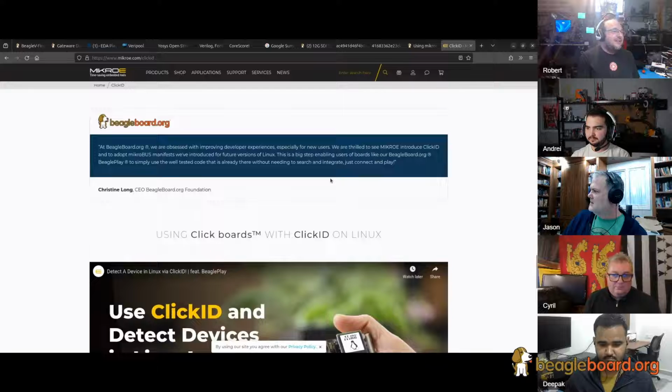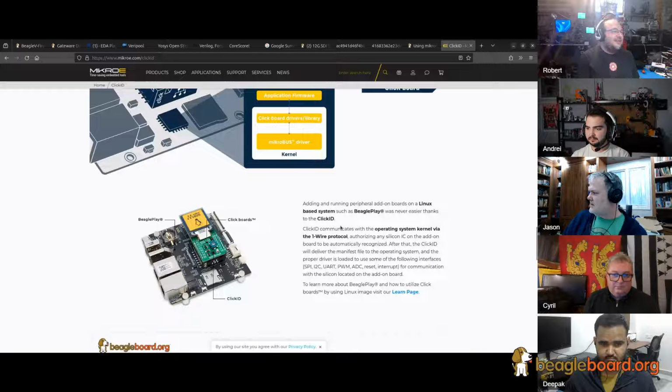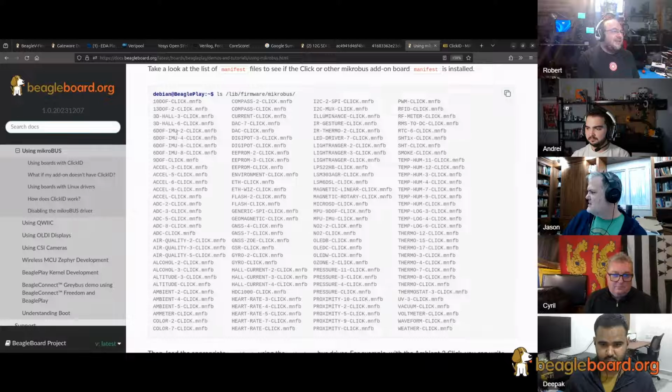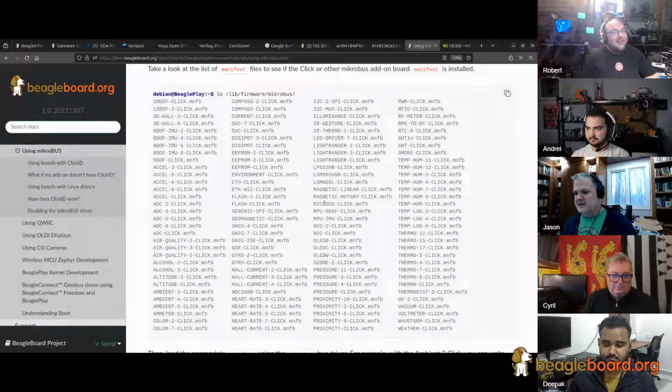All of the driver loading information is what we provide in the manifest, right? So this is the manifest. If you have the manifest, you can get the driver loaded and everything just works. You can store these manifests into those EEPROMs, so that on next boot it'll come up. There's just an extra step of actually writing it into the EEPROM the first time. But there are about 15 or 20 or so that come with the manifests already in them, so that when you plug them in, they just boot right up without any manual action at all.